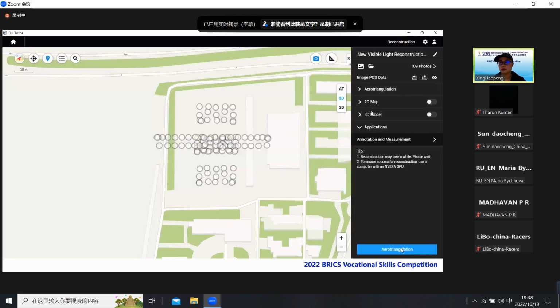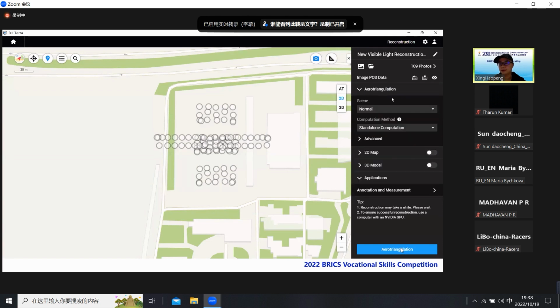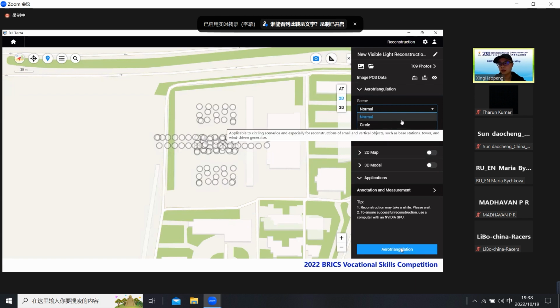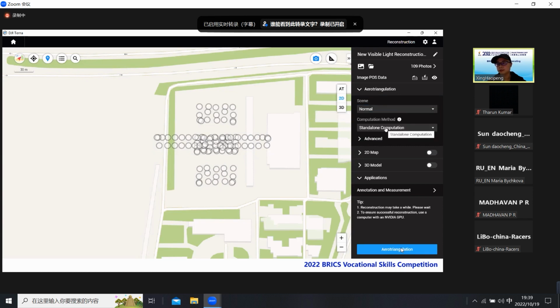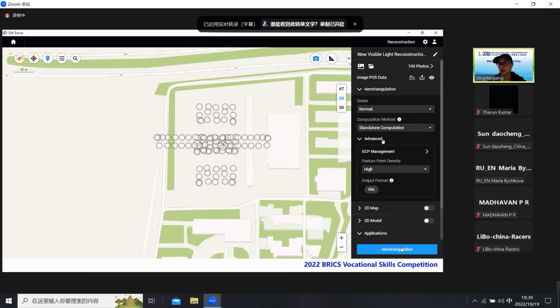Second, the distance from the subject. If cluster calculation is used, the subject distance setting item indicates the distance between the camera and the subject when the data is collected. If there are multiple different distances, the shortest distance is taken. And the larger the distance of the subject object, the slower the aerial triangulation solution calculation is.